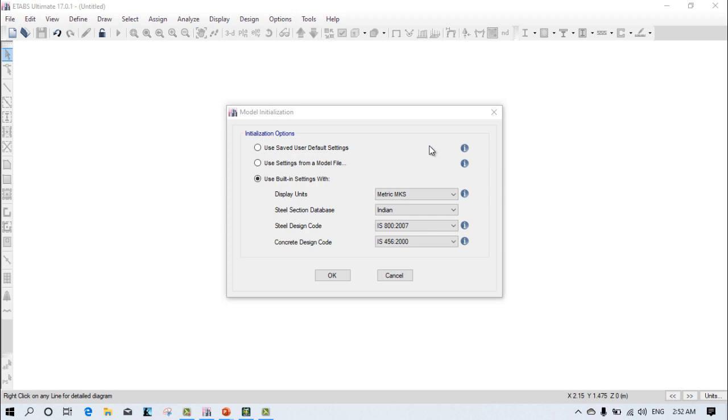So in the last lecture we saw that when we provide a hinge support to a beam, it never restrains in the three directions. It always provides support to the forces, but not the restraint condition. It allows movement along the XYZ directions. But if you provide a fixed support, it always provides the restraint condition in all directions, and also the support condition to the forces. So what we have to do in this video is provide fixed supports at both ends, and the intermediate supports will be hinge ones. Let's see how the behavior of the beam can be identified.